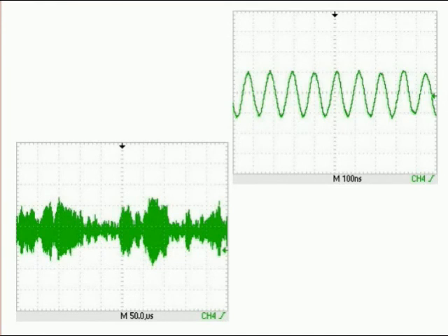Now, in the derivation of the Leeson equation that we're going to do in the next video, we're not concerned with the amplitude noise to carrier ratio, we're only concerned with the phase noise to carrier ratio. So how this theoretical model behaves in terms of the amplitude doesn't really matter. I just wanted to show you that the theory does fit with the practice. So what we're saying is that this theoretical model, as far as the phase noise is concerned, will behave the same as a practical oscillator, but in terms of the amplitude noise it will behave differently. The amplitude noise won't be removed as it is in a practical oscillator.